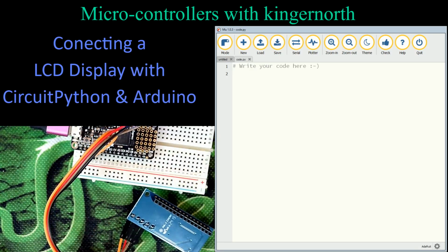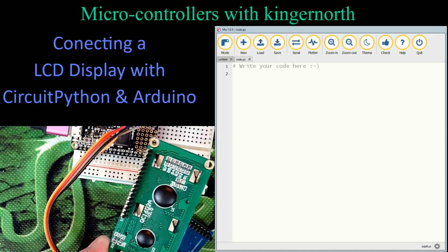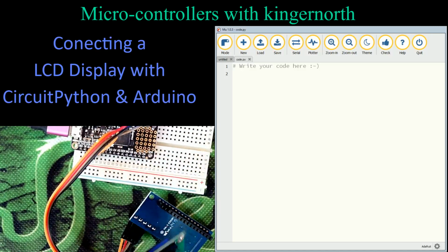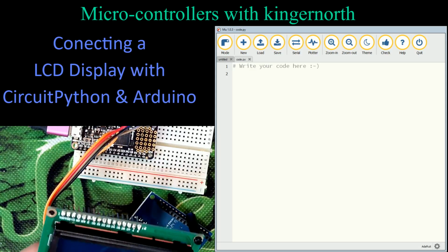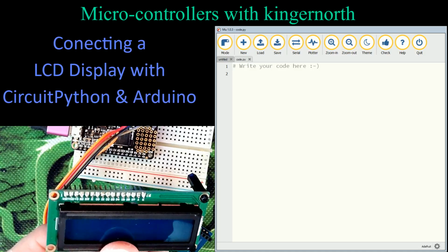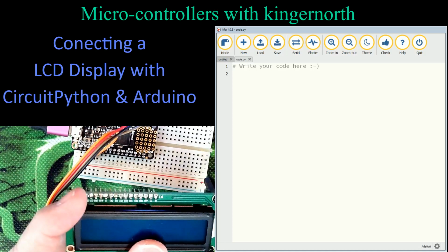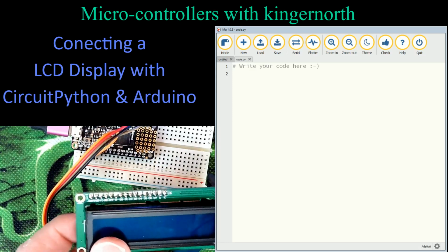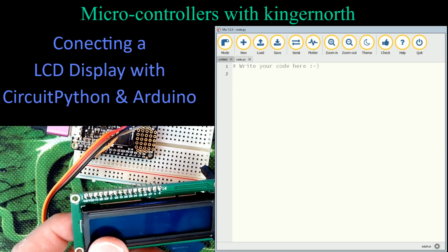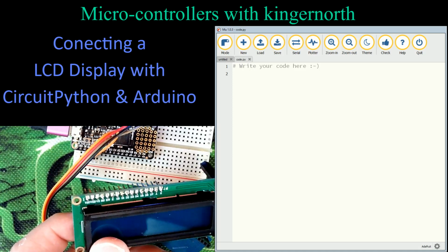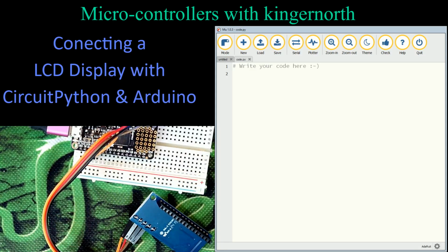when I plug it into my board. When you look at your LCD, all I've done is solder a bunch of pins on, and that just connects to those pins in the row on top of the LCD. Now, there's typically 16 pins along most of these. Some of them have more, some have less. But typically these are 16, so you have to be careful when you're buying your LCD. It should come with all 16 of those, and then they'll connect to one of these boards.